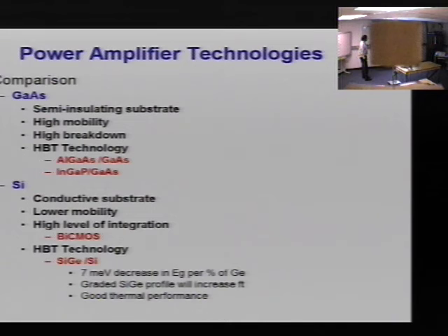What they do is this technology called heterojunction bipolar technology, which is basically a bipolar device, and they have an emitter which has a relatively higher band gap and allows for very high betas on the device, and allows one to dope the base very heavily so that it can handle very, very high currents. So it's a really good technology.